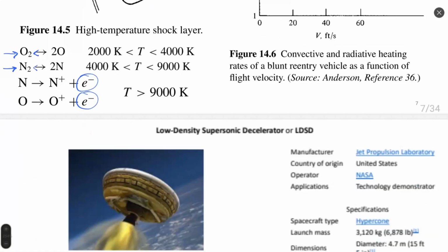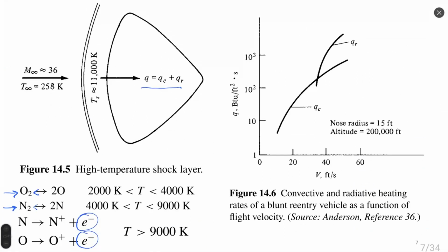This is why we must take into account ionization and recombination and dissociation in any hypersonic flow. It's obligatory when you calculate hypersonic flow to include the complete set of equations describing this process inside the calculation of flow, together with the flow equations.